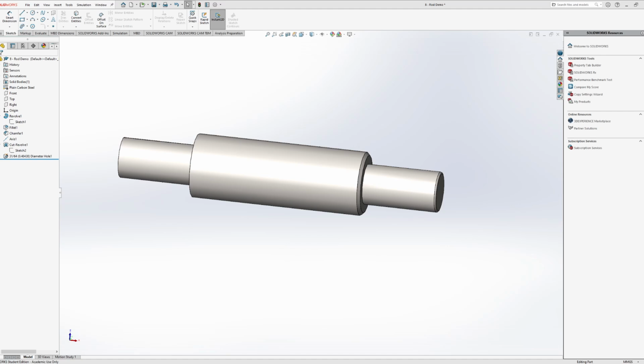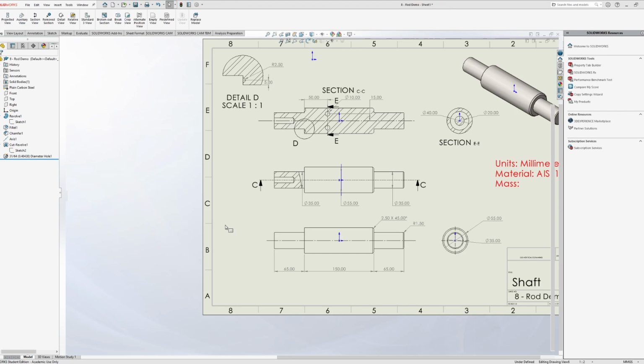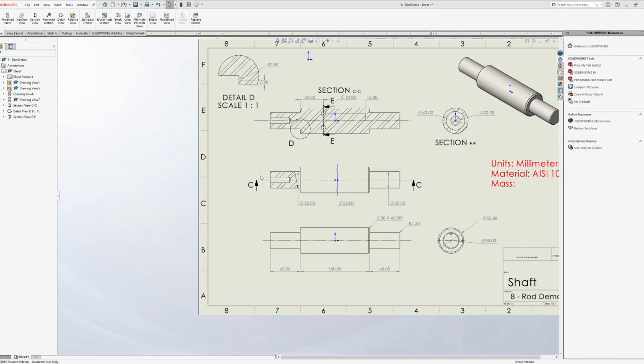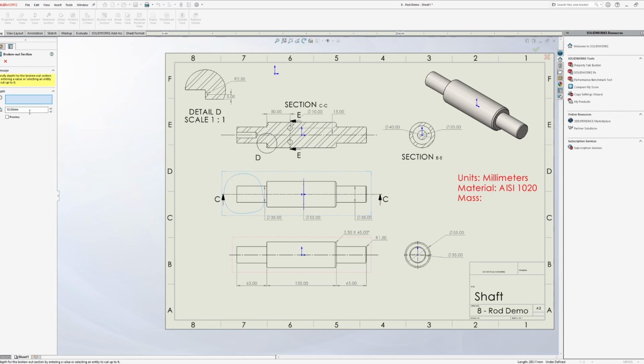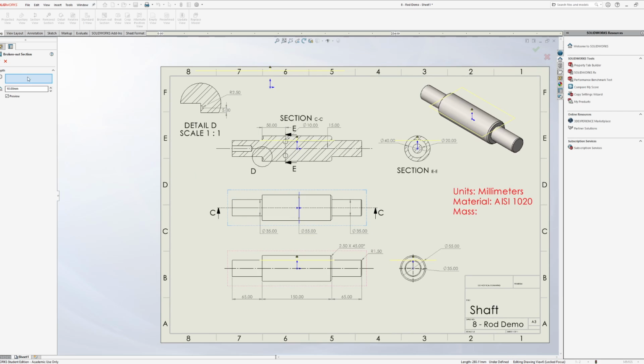Man, I should have mentioned that earlier. It's a cool thing. I think you can also specify the depth. You can either choose an edge that is relatively self-explanatory for where the cut should be, or you can just choose a depth. So if I click on this and do broken out section, I think it might even still work if I choose a depth of 10.